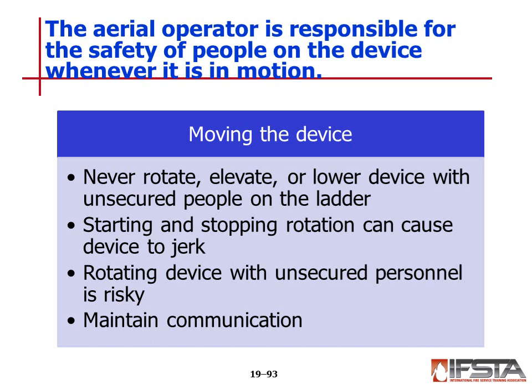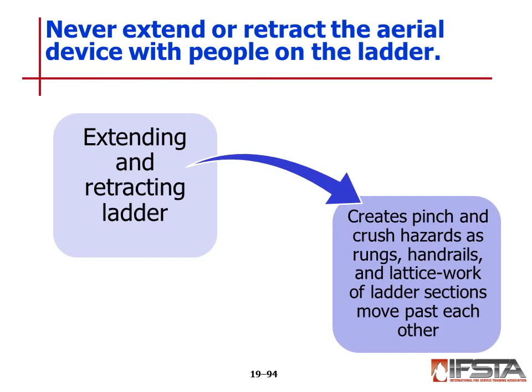Maintain communication between personnel and always notify personnel on the device before moving it. Never extend or retract the device with people on the ladder. Extending and retracting the ladder creates pinch points and crush hazards as rungs, handrails, and other members of the ladder section move past each point.